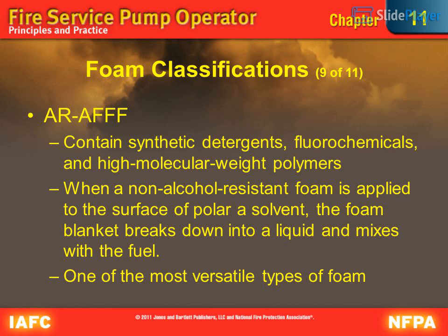Foam classifications, 9 of 11. RFFF. Contain synthetic detergents, fluorochemicals, and high molecular weight polymers. When a non-alcohol resistant foam is applied to the surface of polar solvent, the foam blanket breaks down into a liquid and mixes with the fuel. One of the most versatile types of foam.